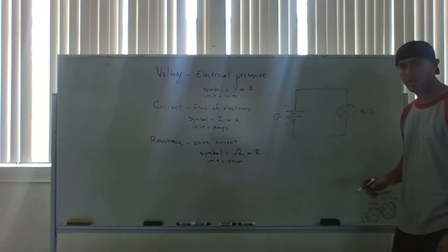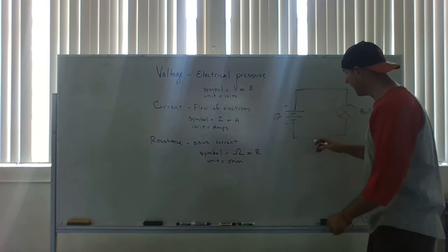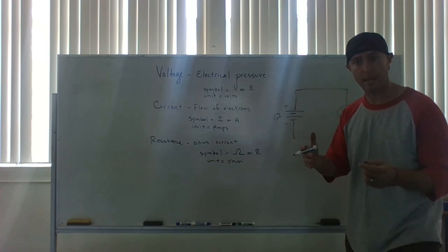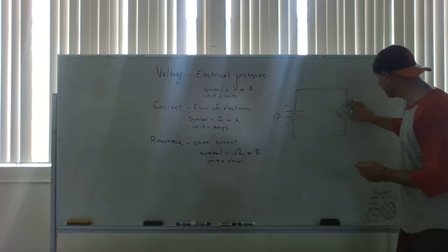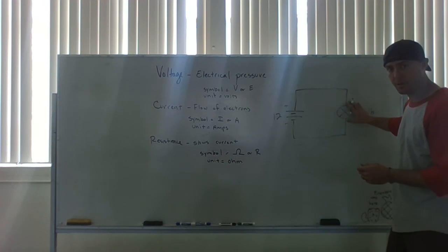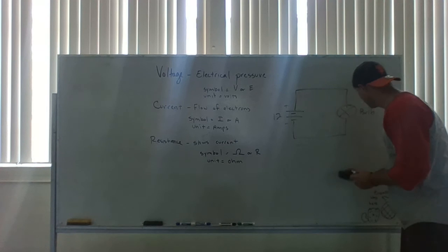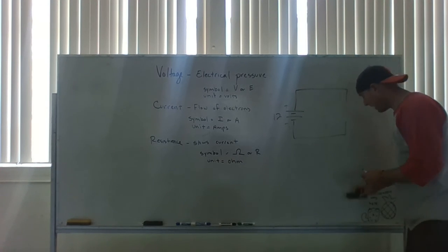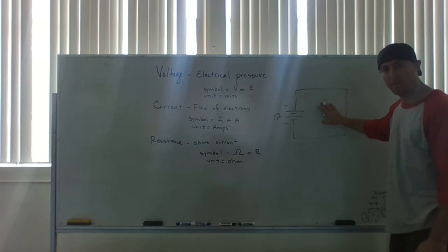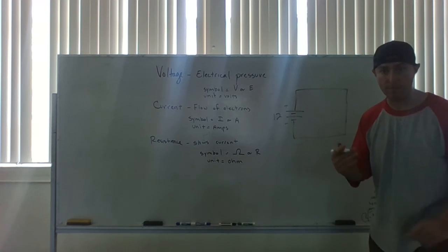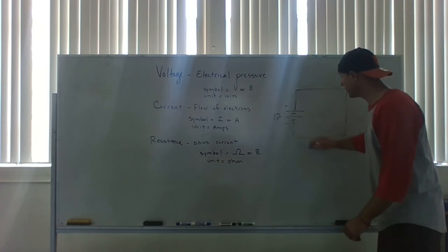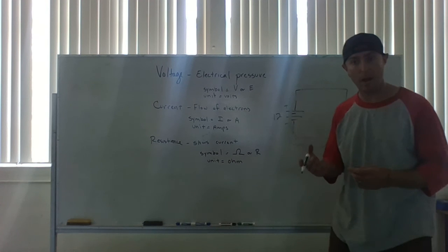All right? So now I have current going through here, it's turning on my light bulb, it's a safe circuit. We've measured everything, we understand the amperage load that this bulb can take, all right? And we have enough resistance, so it's going to be a safe circuit. If for some reason this light bulb was taken out of the equation and I had no resistance now, I have nothing that's called a load, I have nothing that's using the electrons, they're going to jam around here so fast, all right, it's actually going to heat up that wire.